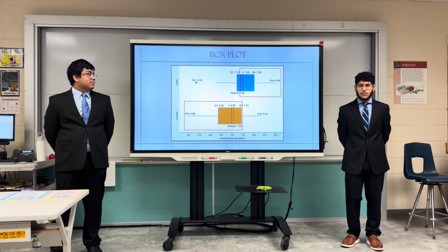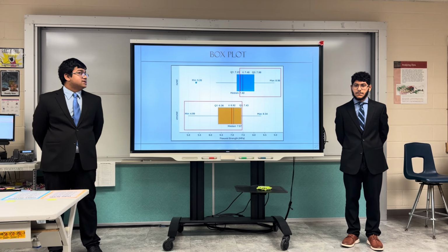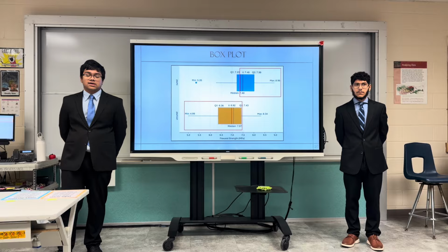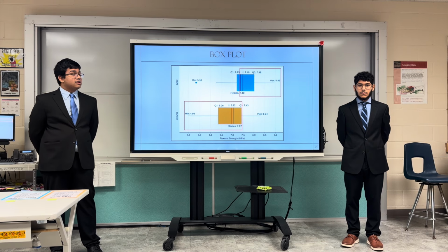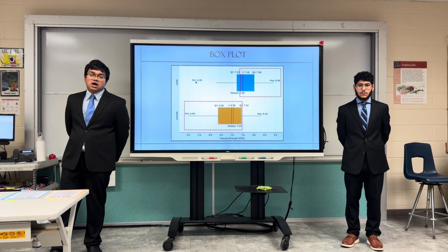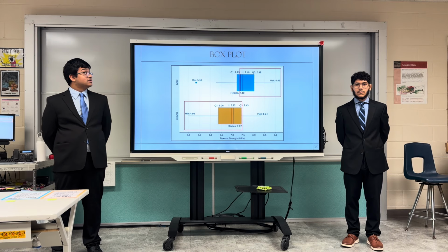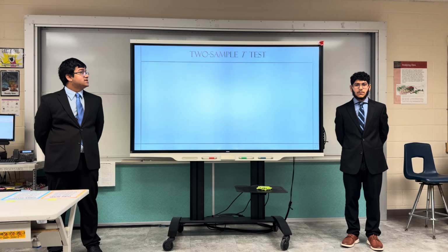Finally, we can talk about the overlap between the box plots. As you'll see here, 50% of the cured concrete's data is above 75% of the uncured concrete's data, which suggests that cured concrete may indeed have a greater flexural strength. However, it's merely a trend, and in order to confirm this, we had to perform a 2-sample t-test.